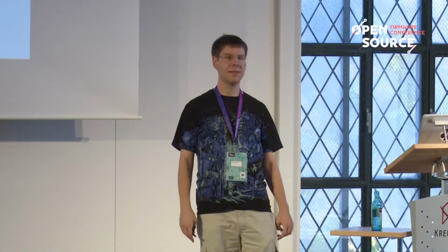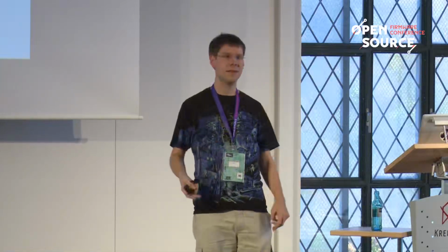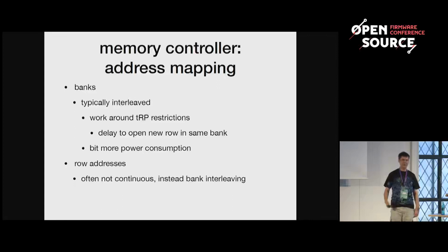And then you basically can mask the latency, because when the one row is closed, the other is already opened, and then you can just continue reading or writing the memory. And yeah, having more banks open also increases the power consumption, but gives more throughput.